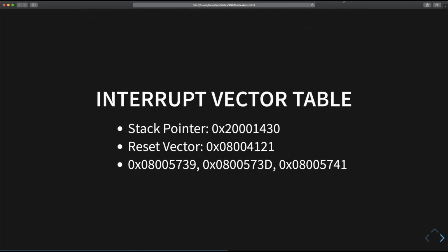So when we decode these, we get first the initial stack pointer, which tells us which piece of RAM the firmware is using. And then we get a bunch of interrupt handler addresses, beginning with the entry point of the program and continuing on to other events, like receiving a byte on a serial port or having the NMI pin or non-maskable interrupt tapped.